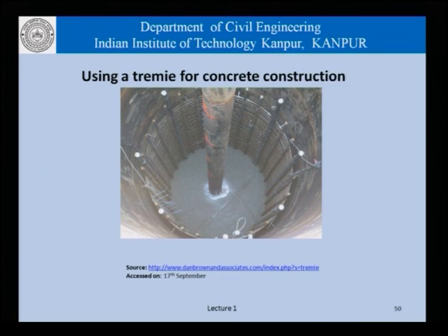Concrete is allowed to fall through the pipe, and it needs to be ensured that the pipe is always buried in the concrete that has been placed. As more and more concrete is placed into the formwork, it rises up and gradually fills the total space, completing the construction process.